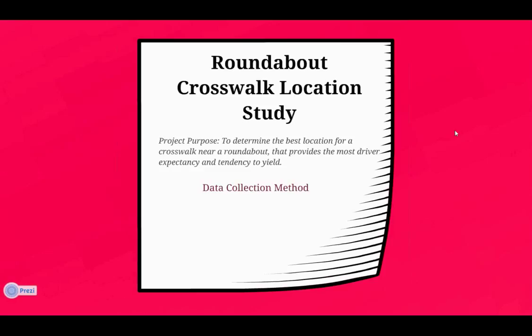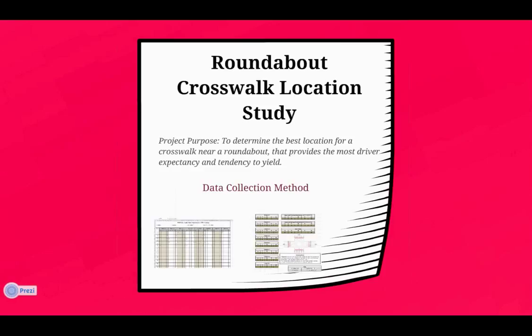Third, and probably the most important, is the condition assessment and the rating system. How is the condition of these walls assessed? Are they using the new LiDAR technology, which will do a scan and give you a 3D image of the wall itself? Are they using a tilt meter that they can place on the face of the wall, or are they just doing a visual inspection?